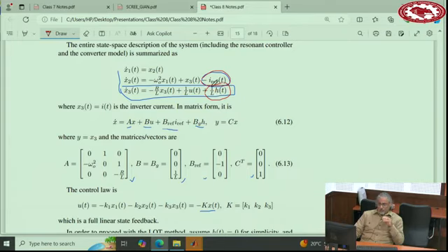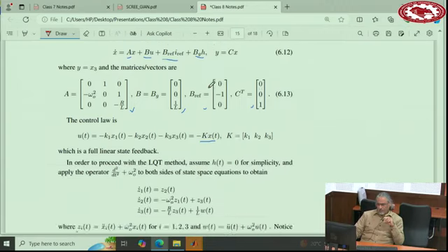H is harmonics, but i_ref is a fundamental. So in general, if you want to remove harmonics and fundamental at the same time, it will be complicated. Let's start simple. Assume that harmonics are not there, or they are so small that we do not care at this point. We only have this term, sinusoidal at frequency 60, okay?